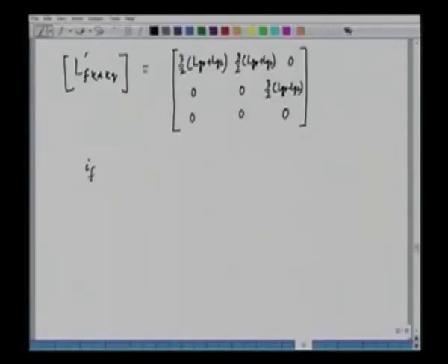By this special transformation, the currents of the rotors also get changed. The voltage of the rotor also gets changed, because we are referring everything from the primary side in the dq reference frame. The rotor current If prime is equal to 2 by 3 times Nf by Ns into the actual If. You can see that a factor of 2 by 3 comes in, because the rotor is a 2-phase rotor and the stator is a 3-phase stator, and when we transform to the stator side, a 2 by 3 factor comes into the picture.